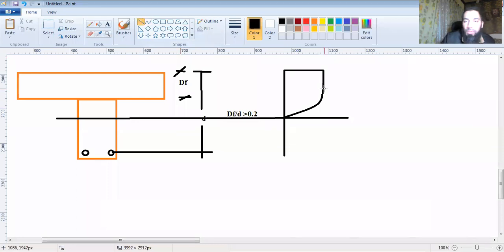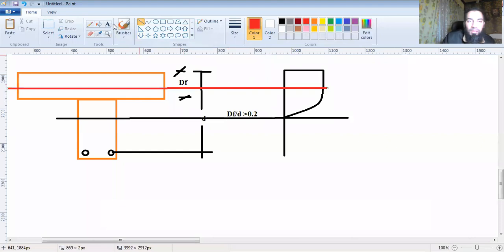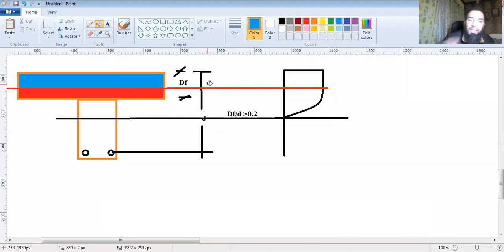Now, if you check up till this point, it's linear. And then, so this much portion is in nonlinear, and this much portion is in linear zone of the flange. Then all of the portion of this web above the neutral axis is in nonlinear zone of the stress block, and this would be in tension.